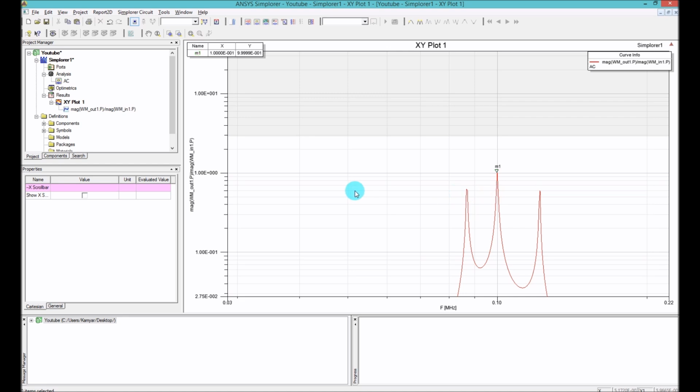Well, no doubt, because the distance is pretty small, so it's 99.99%, which is actually true, because I checked with the WPC standard and they were saying that in some cases you can get more than 99% efficiency. Of course, we are not taking care of the quality factor of the coils.